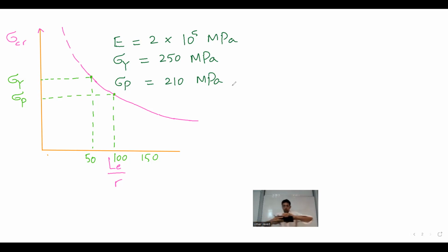I will answer your question. In parallel, I will write. Yes, please. Well, in fact, I can stop. In which part will the yielding and buckling appear simultaneously? Yeah, in the vicinity of 100. In the vicinity of 100, all the way from 95, 96, 97, in that critical zone, or probably 2-3 values above and below, the combination will happen.